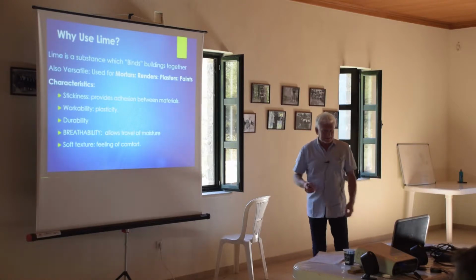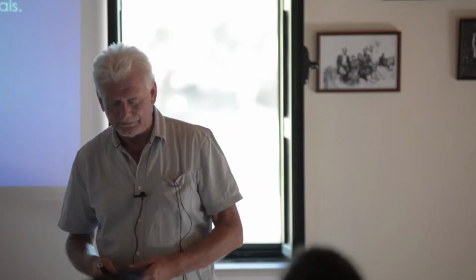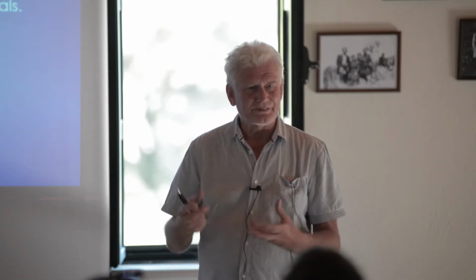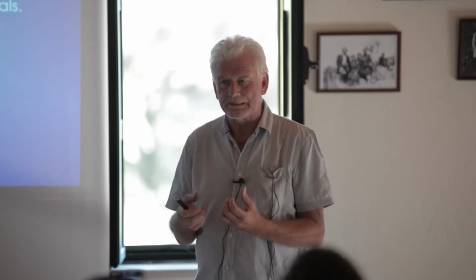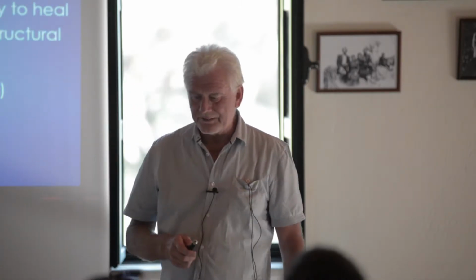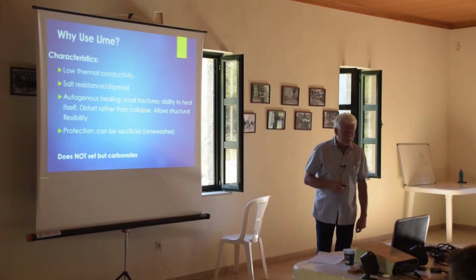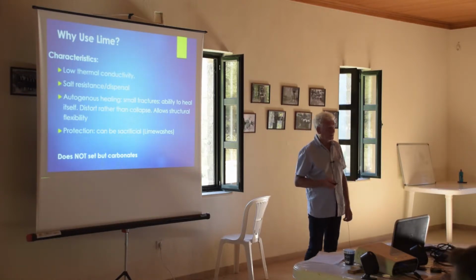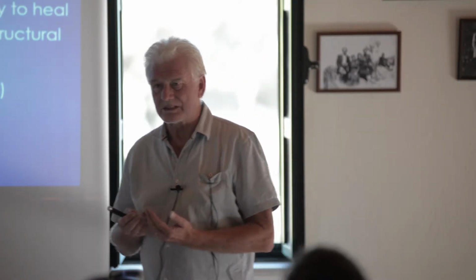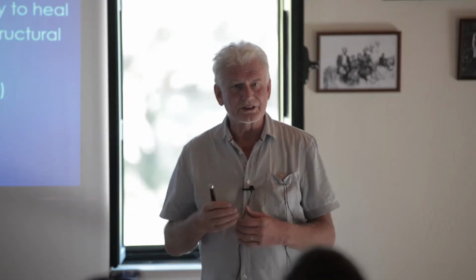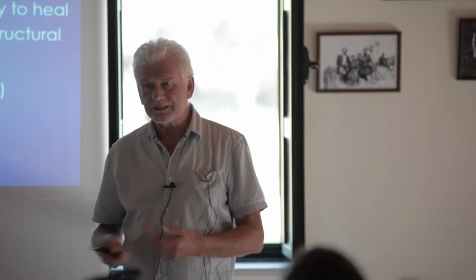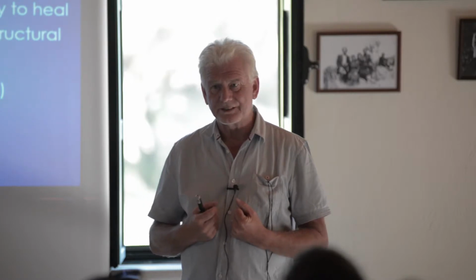It has a very soft texture, and traditionally older properties, particularly cottages, small houses, etc., have a particular feel about them, a particular warmth about them through the use of this material. They have very low thermal conductivity. So when it's really hot out there, and you go into a house that has been constructed using lime, it's nice and cool inside, yeah? And during the winter, it's the opposite. It holds heat within the building.